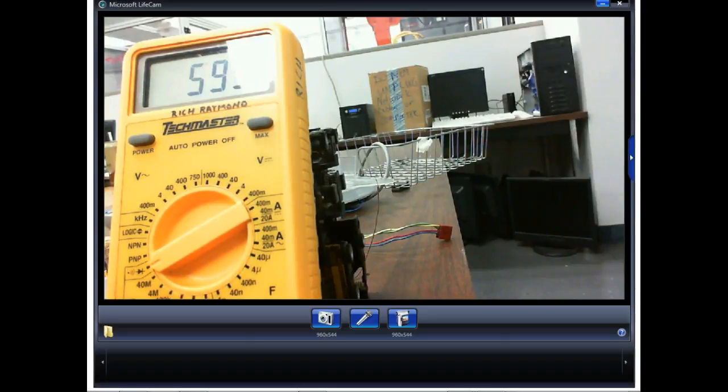Oh, y'all can't see the last digit. So this means this diode's good. But look, it only measures when I forward bias it, right? You understand? When I reverse bias it, it gives me the same thing it gives me when I'm not even touching.